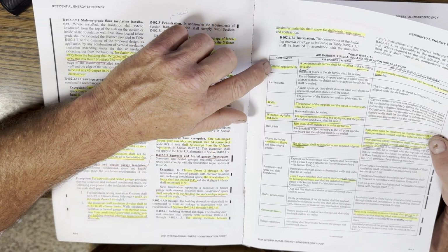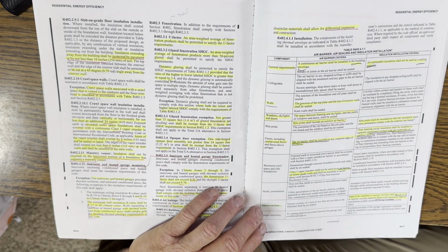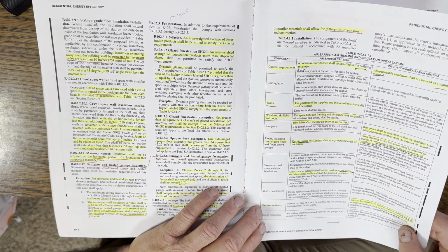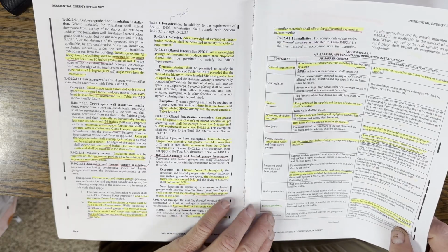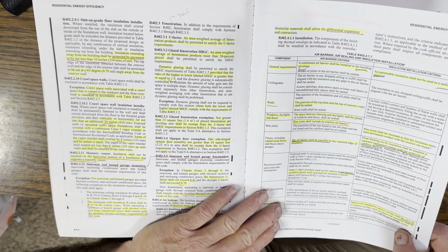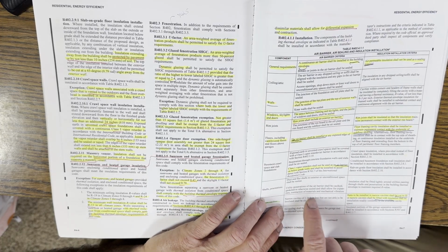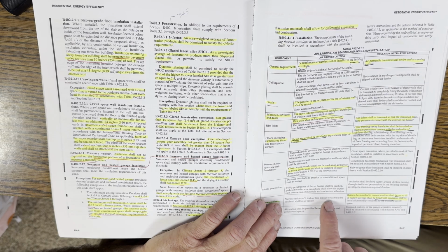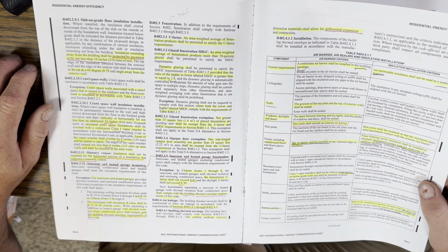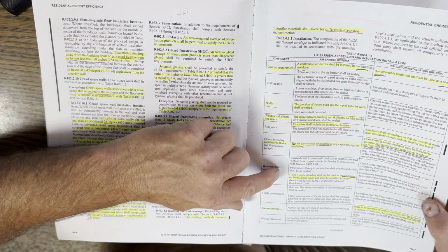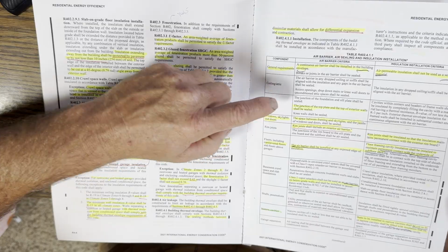You did have some questions from table 402.4.1.1, specifically narrow cavities. There was a multiple choice question about insulating regarding the thermal envelope. All you had to remember is that narrow cavities have to be air sealed. Narrow cavities of 1 inch or less that are not able to be insulated shall be air sealed. So that was a multiple choice item in there. I don't remember the question specifically, but it was referenced from this table.